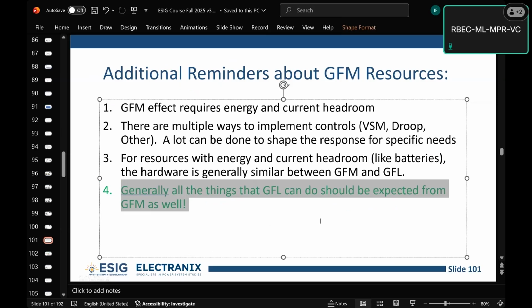So if the voltage step happens, how quickly does your reactive power get injected? It was kind of annoying because the StatCom manufacturers, or the people making the specs, would be like, we want fast, it's a StatCom. And so they would specify something right at the edge of the capability of a StatCom, like 50 milliseconds or something.